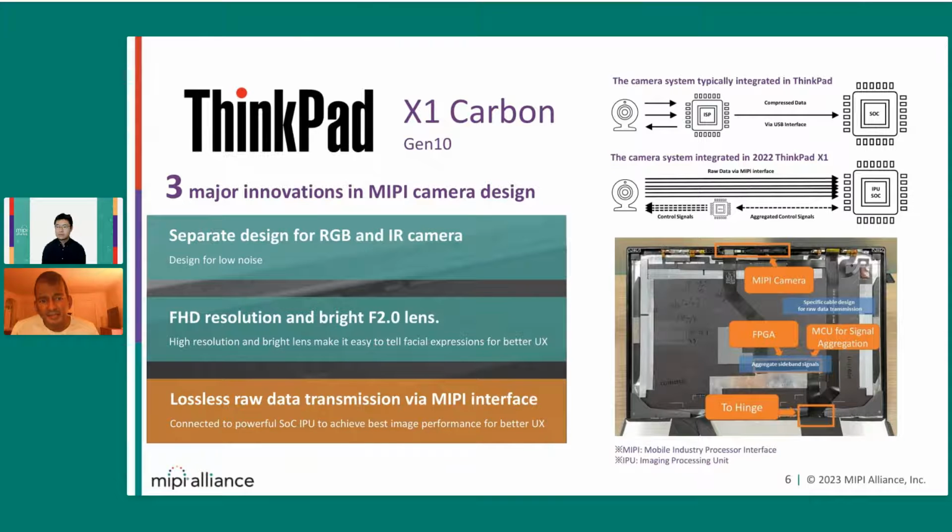The question from Ethan is: when you are referencing USL for client platforms, do you have a preference between the D-PHY two-wire signaling versus the three-wire C-PHY signaling? Yeah, we'll have some research on it as well, but it depends on the SoC or the image sensor support. Recently I saw some sensors that support C-PHY as well, but at that time we didn't see any sensors supporting that.